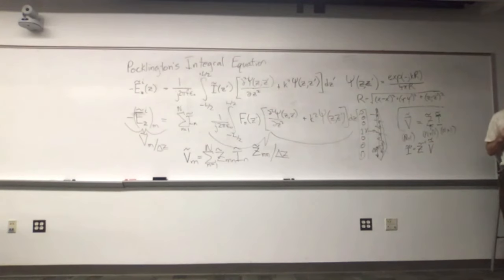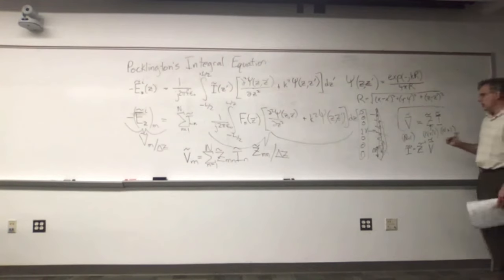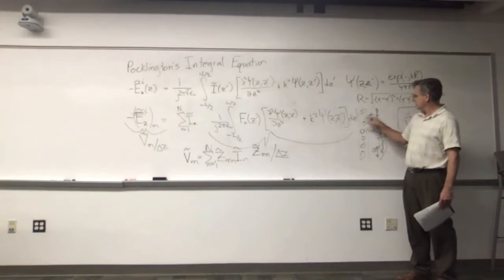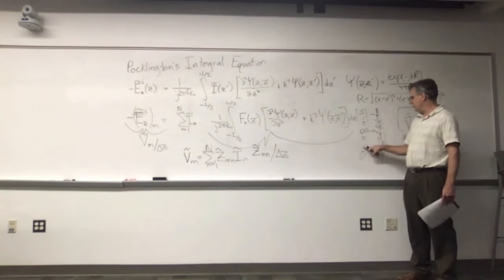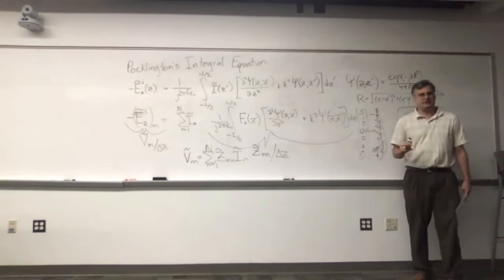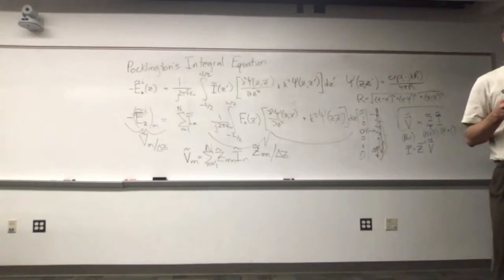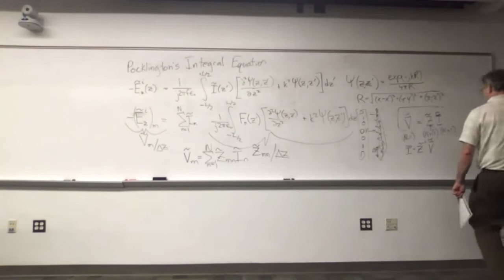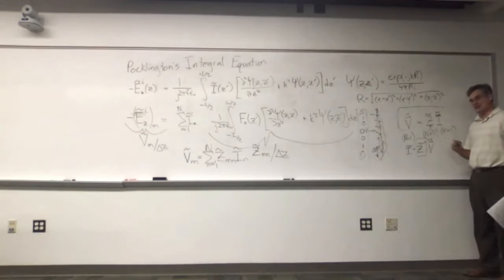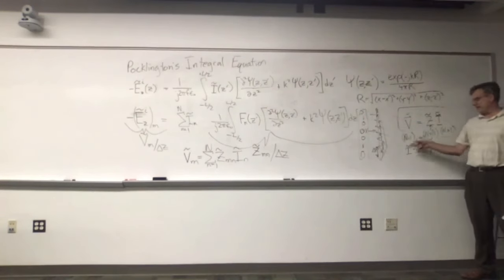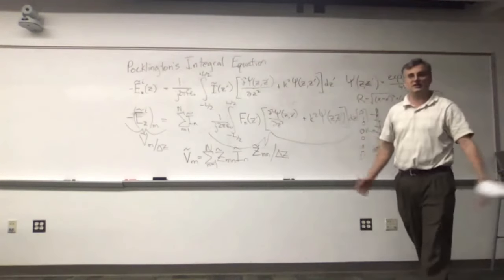And then if you get a crazy idea like, ooh, I know what I'm going to do. I'm going to make a half-wave dipole that I feed like this. I put a voltage source there and another in-phase voltage source down here. Nobody's ever thought to do that before. Let's try to see what happens. What kind of radiating system occurs when you do that? Well, you've already solved this, and in many cases inverted it. All you have to do is populate that vector, multiply your inverted Z by that vector, and you get the new current distribution that falls out of the system.